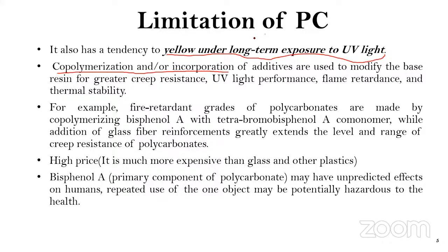Suppose if you heat them for a longer duration of time, the temperature might be 70 to 80 degrees, and you place your material at that temperature for, suppose, 48 hours, you see that they will turn yellow in color, and you can easily break that polymer into two pieces. That means they have turned into the degradation stage, a few of the bonds are broken.